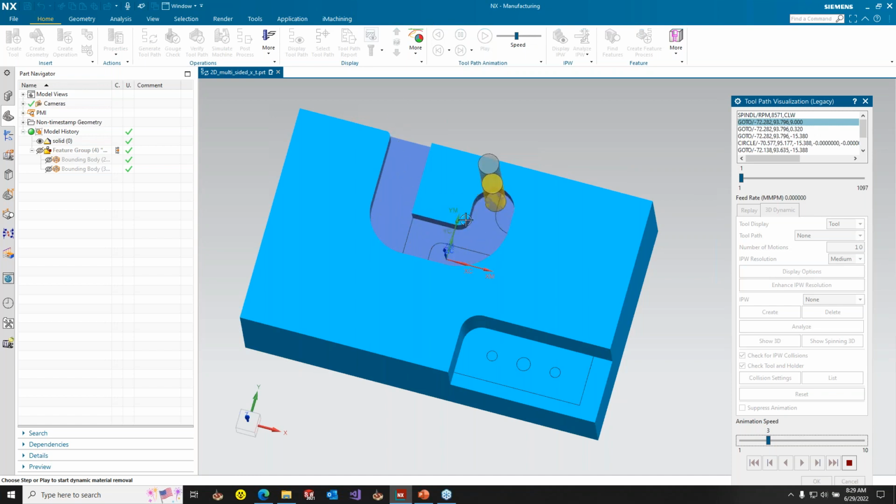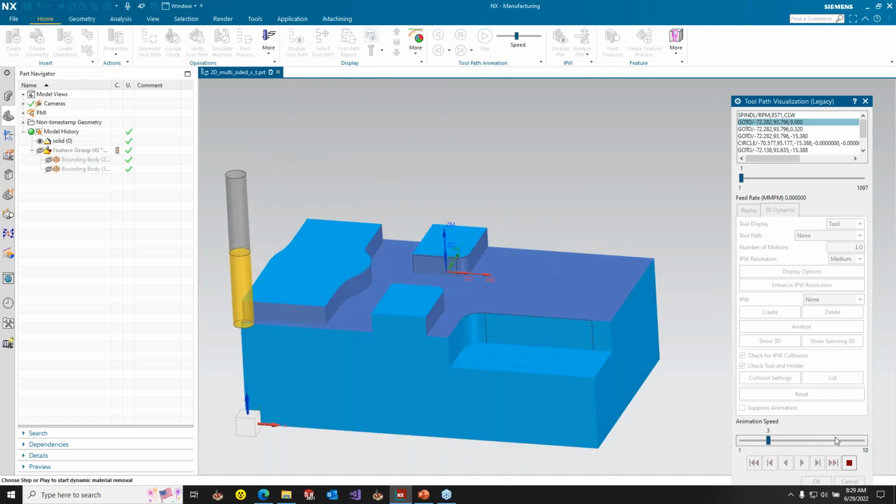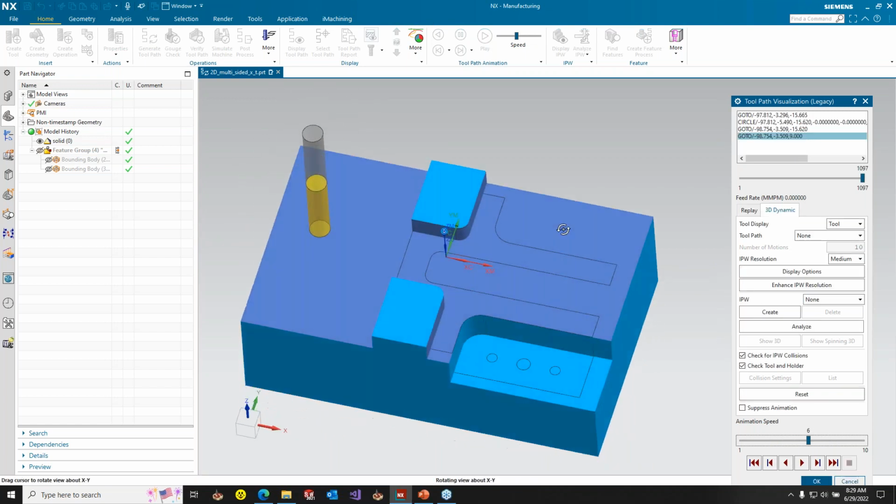So what this does is this channels along the walls. And what this is going to do is this is going to separate the geometry so that way we can machine this area and this area with a spiral toolpath. And in the end, the spiral toolpath is the best for the tool because it keeps the tool moving in the same direction. So here you see the spiral. So we're spiraling. This is the nicest, the least amount of lead-ins and lead-outs, which is the most difficult thing for the tool. And we can speed that up. And there we get our spiraling toolpath.